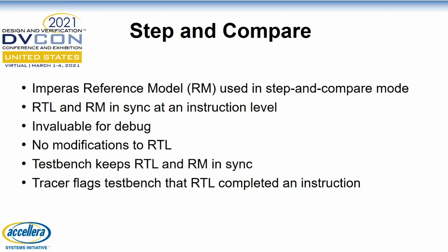The test bench is what's going to keep the RTL and the reference model in sync. And the tracer, which again Steve talked about, will flag to the test bench that the RTL has completed an instruction and it's time to compare those results against the reference model.